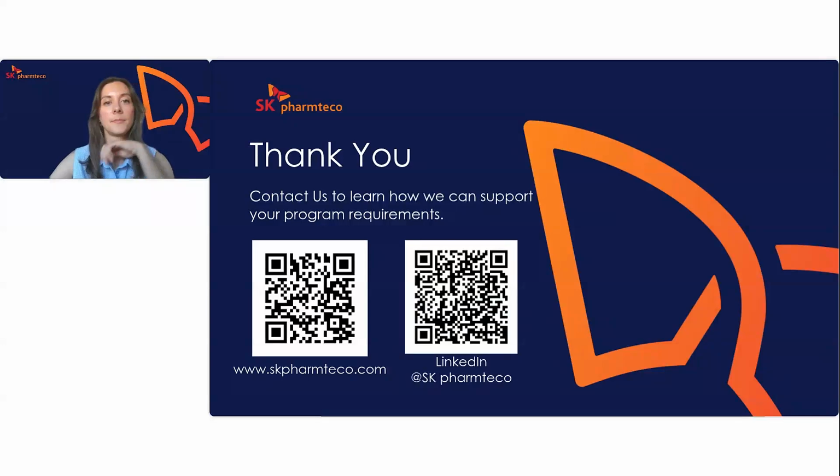So some of the common issues we've seen are not thinking about intermediate stability. At benchtop, it can take a few hours to do a process or certain stages of a process, but when you scale that to manufacturing, it can take much longer. So it helps to build intermediate hold studies into your early development studies for a realistic approach, if you know certain steps are happening on which days, where you need that stability data.